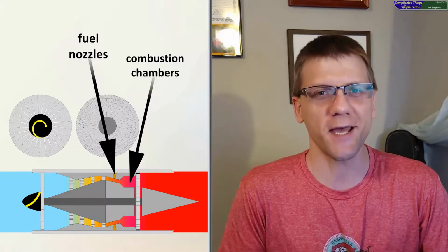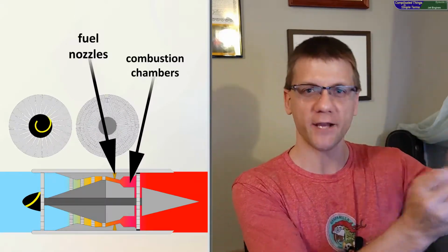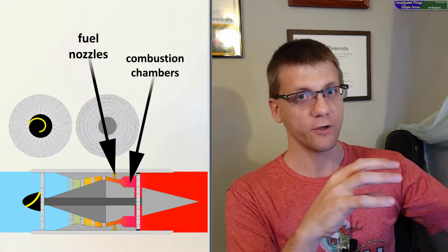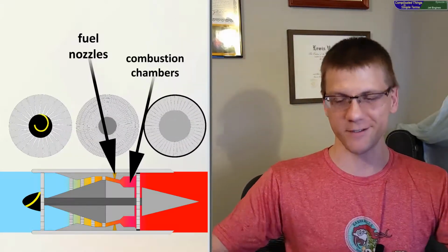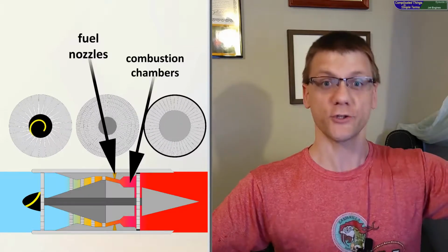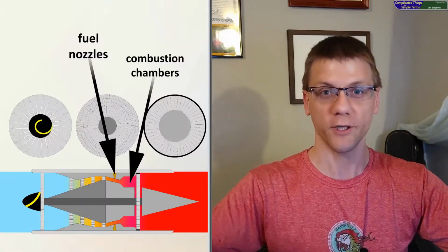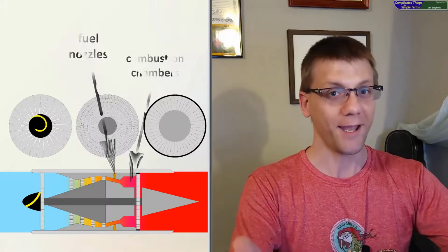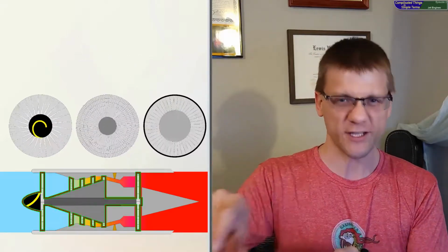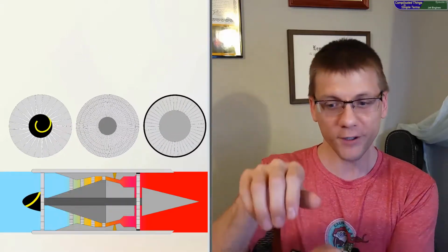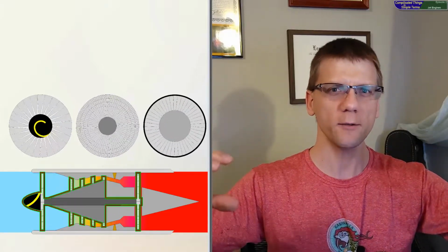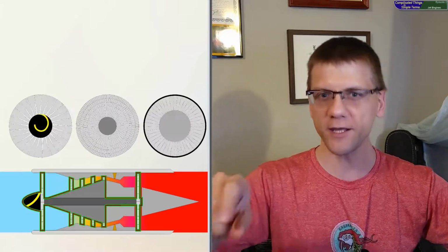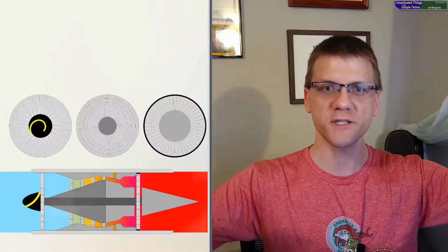But at the same time, you're jetting all of this energy out the back of the engine, so you have it go through the turbine. But remember, that turbine is connected to the fan at the front. So it turning really quickly turns the fan really quickly, which sucks more air in. And better yet, all the little compressor sections that were just described, they're on that same single spool. So the whole thing is basically one big moving part. The fan, the compressors, the turbine, it all just spins and it's all attached to one rod at the center.